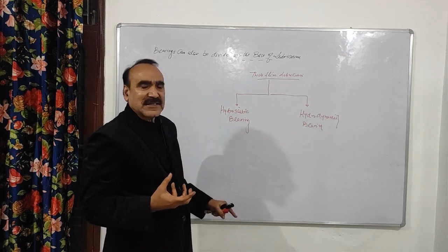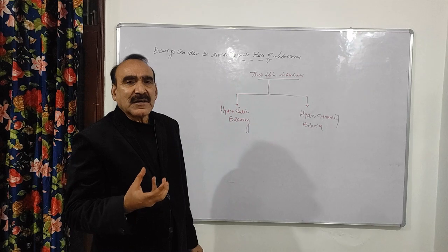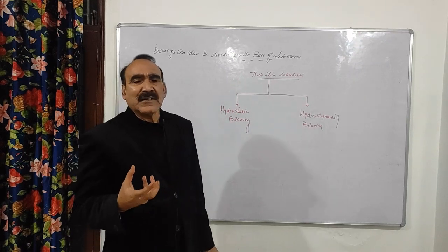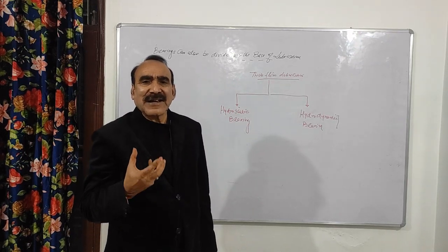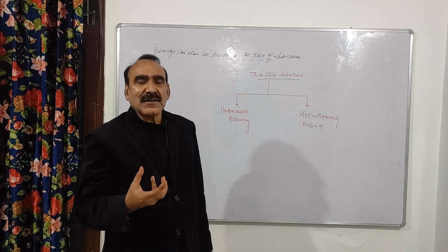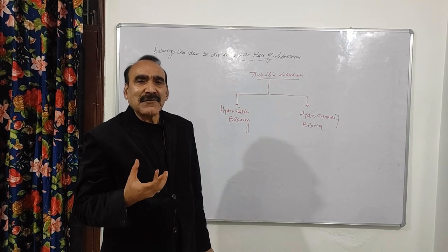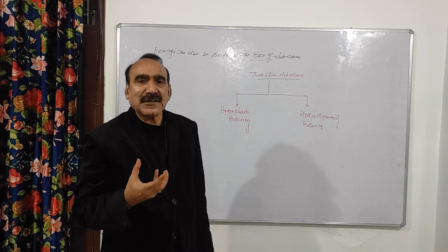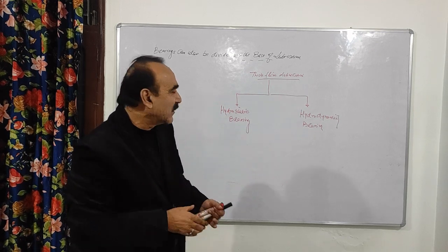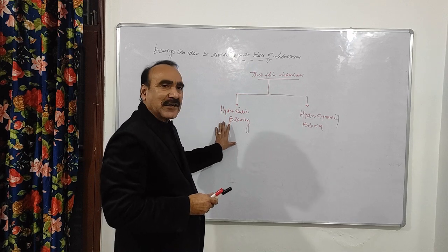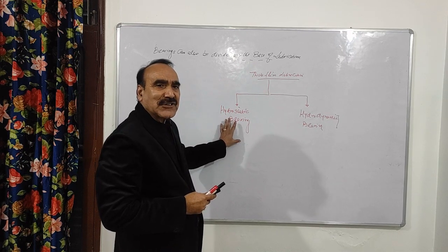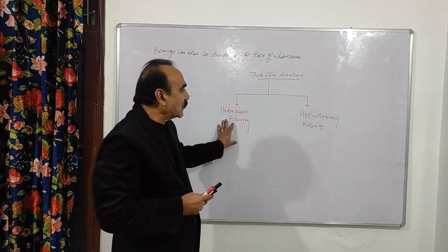So in this case, even if the shaft is not rotating, even if it is at rest, still there is a thick film formation, and there is a thick film formation with high pressure. The thick film formation is there, right? In case of hydrostatic bearing, this is the way the pressure is created, and this is the difference also.